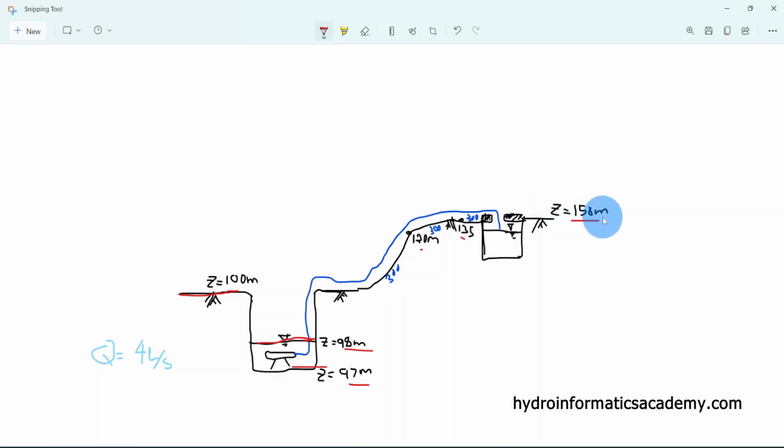As I said, we are pumping water from this point to this point, 4 liters per second. So for the length values, from this point here all the way to this point, the length is 300, and from this junction here to this junction is 300 meters, and from this point here all the way to this point is again 300 meters. So we want to size this pump for this network, of course, by using our WaterGEMS software. Let's see how we can achieve that.